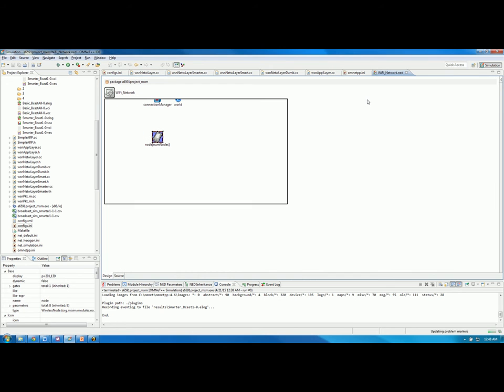In order to do that, I needed to develop my simulation environment, and this is where the connection manager controls the various physical layer connections between the different nodes, where we can set the number of channels to use, what channel number, the frequency, etc. And our world manager here simulates the environment that we're simulating in. Do we want obstacles? Do we want to model free space? Do we want path loss? Or some interference from something, noise levels, that can all be configured in the world.